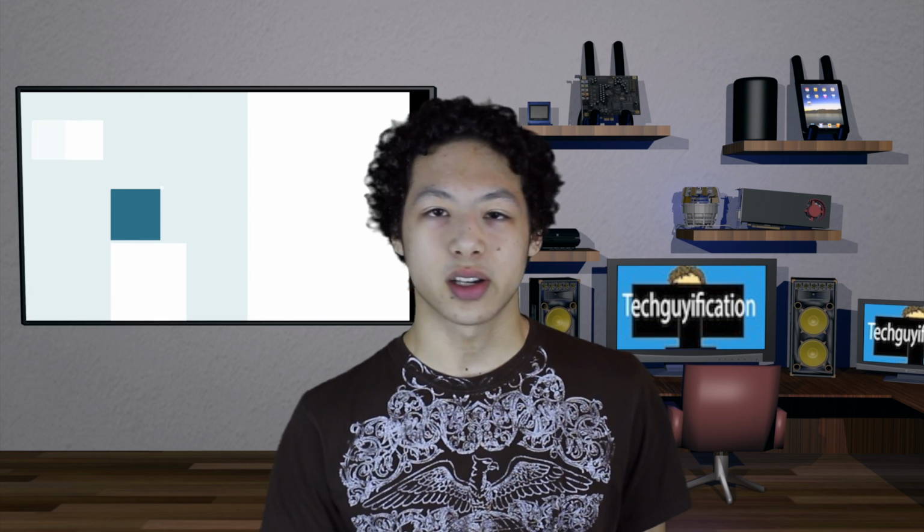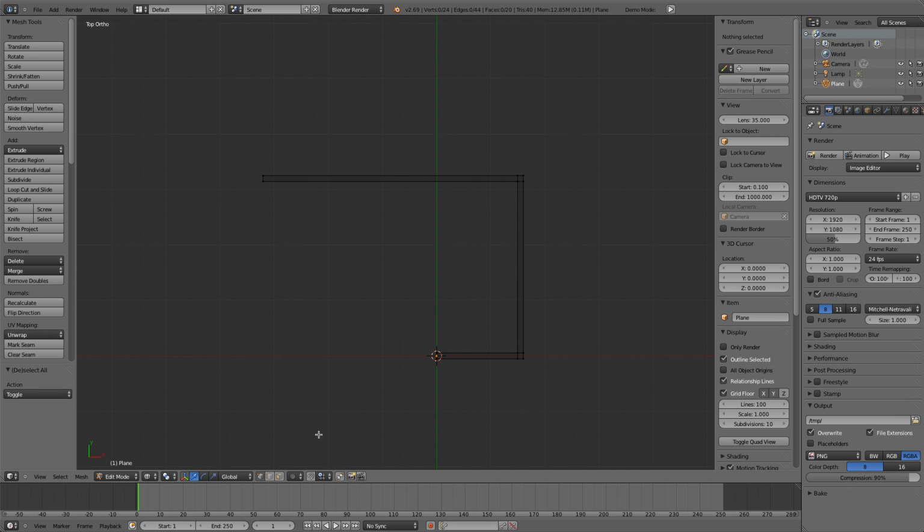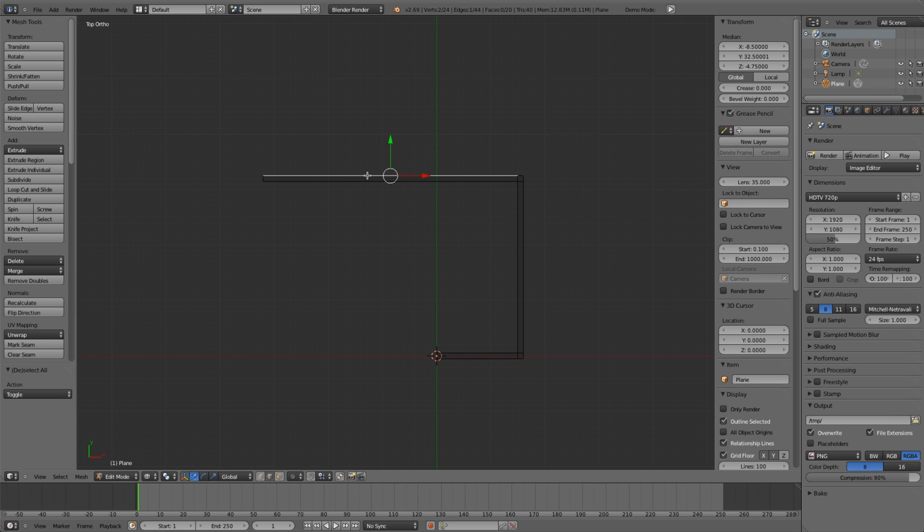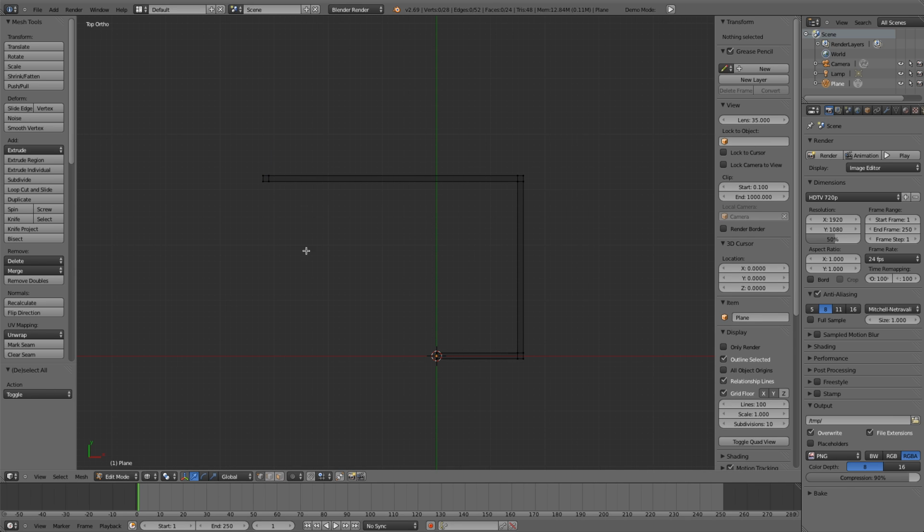Press the A key to deselect all the vertices, and select one of the top edges, and then hit Control E, edge ring, and then we're going to hit Control R, and we can place our subdivide thing vertically. So now left click once to accept it, and then in the X median, make sure it's set to global, and set it to -31.